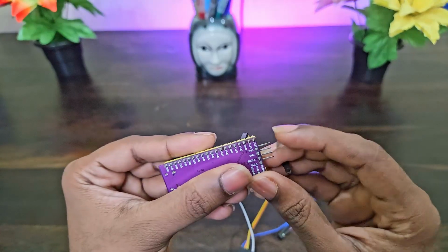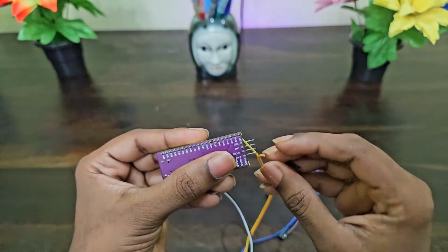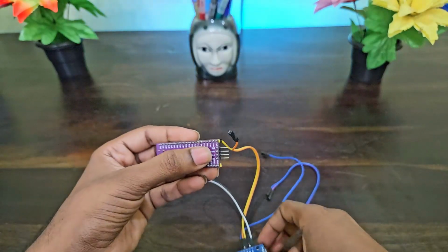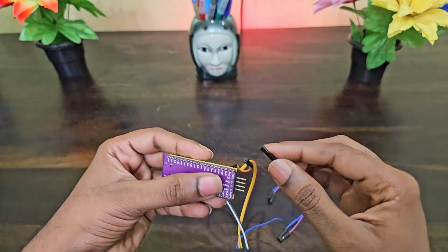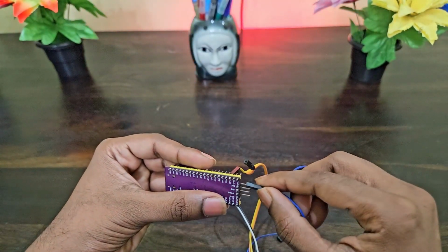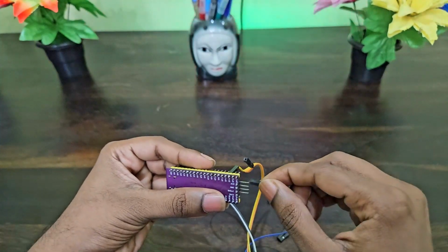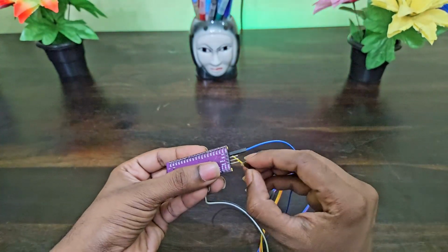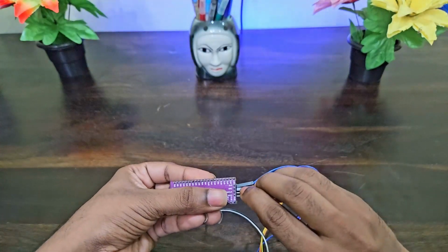Finally, ensure proper power connections for stable operation. Connect the VCC pin of the module to the 5V pin on the Raspberry Pi Pico. LED modules typically require 5V to maintain stable brightness. Finally, wire the ground on the module to the ground on the Raspberry Pi Pico. Please complete the circuit and ensure a common ground.